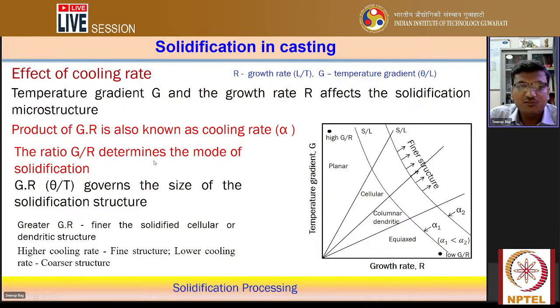It means whether it is a fine structure or a coarse structure. So the greater the G into R, the finer the solidified cellular or dendritic structure.